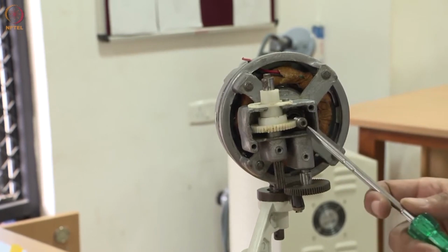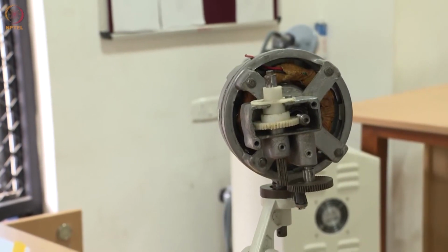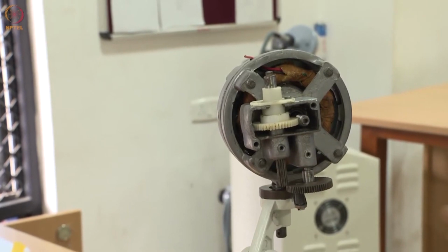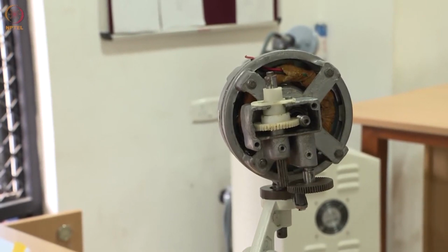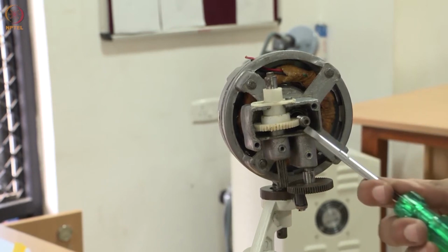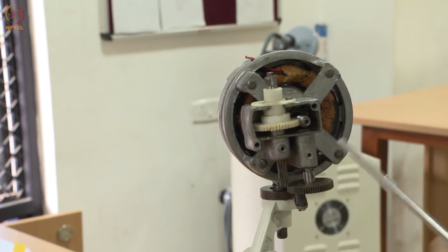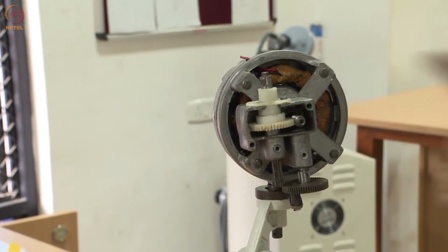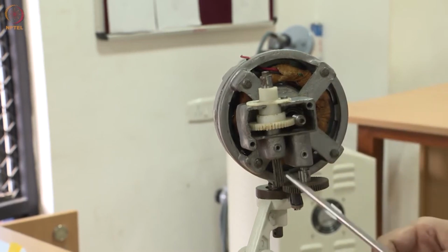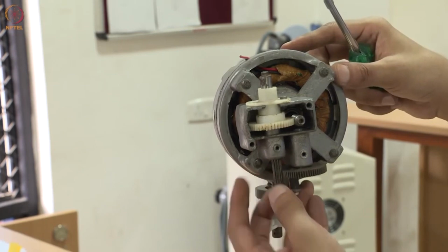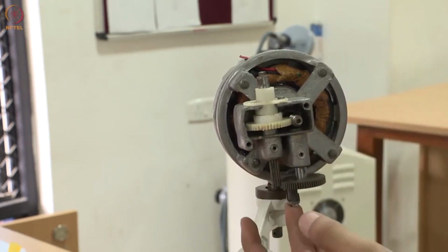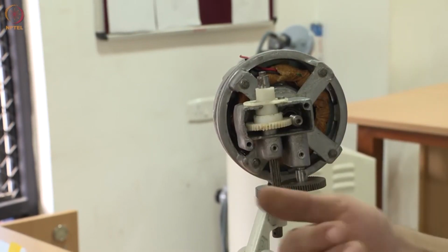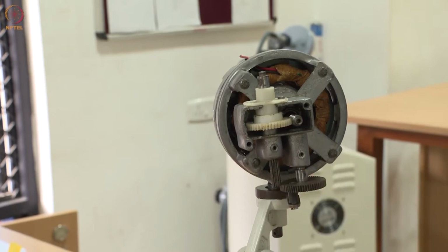In the first reduction between the worm and worm wheel, typically somewhere around 1:75, that is the gear reduction, which means for every 75 rotations that the main shaft makes, that is the worm makes, the worm wheel will rotate once. So again, we have another reduction here in series. There are two gear reductions in series, to give us a very large gear reduction, and which also amplifies the torque.